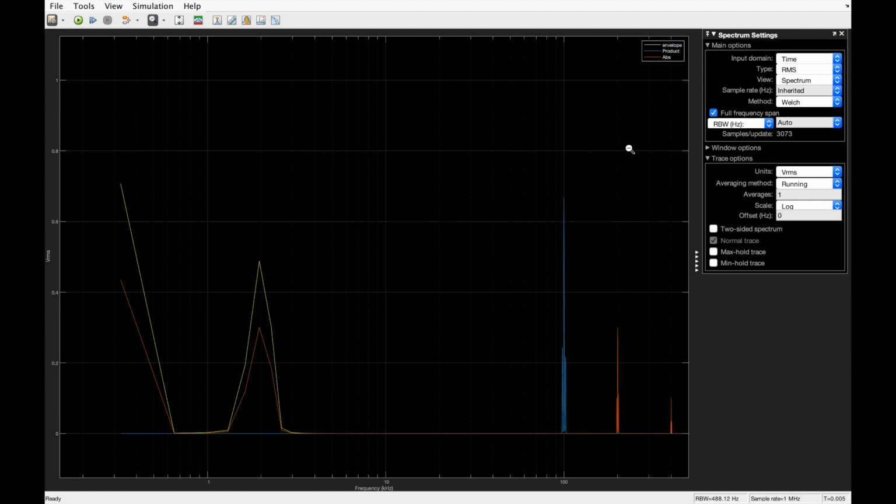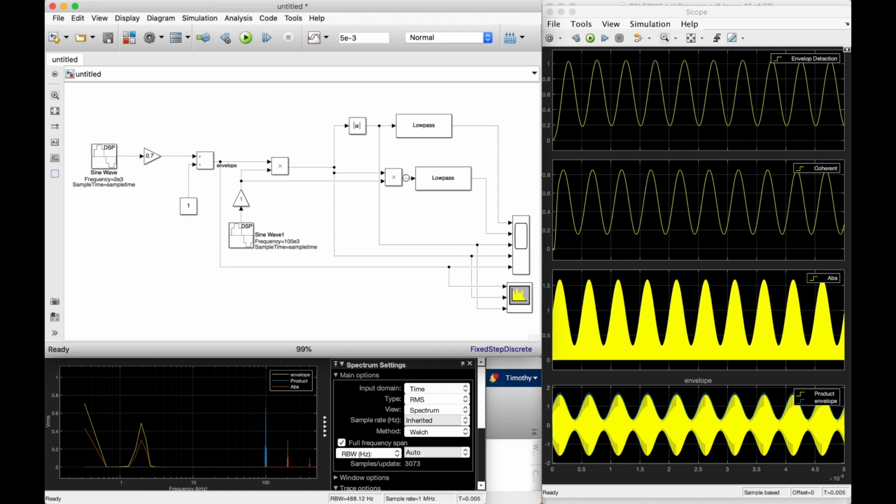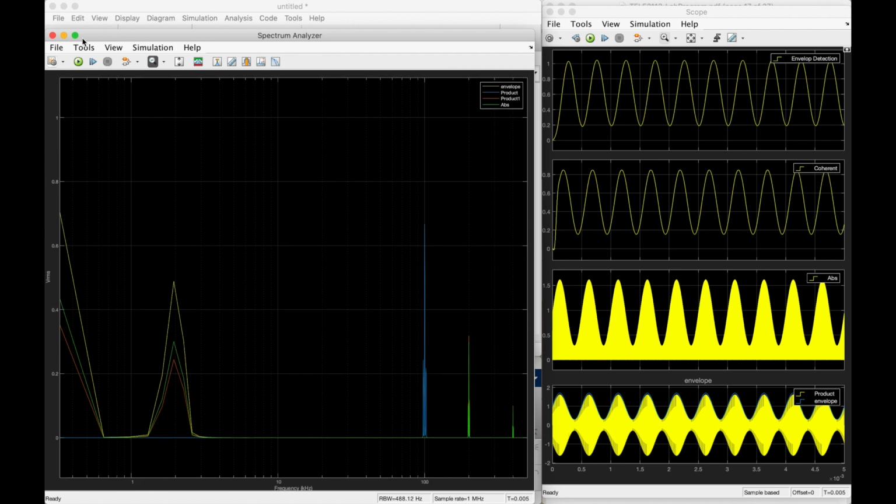Okay, and then once we perform the absolute value of that, we can actually see that we still have this component of our original signal, which is the same as our envelope, but we also get these copies that are produced, these higher frequencies. So what I want to do is I just want to show what the output now is from the multiplier. As you can tell, my computer's struggling with this a little bit. Great, okay, so we can see the multiplier. Again, it shifts everything back here, and it also gives us copies because it's multiplying by that 100 kilohertz again.